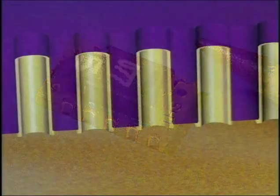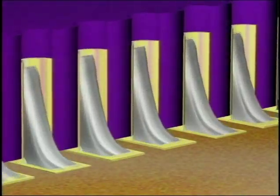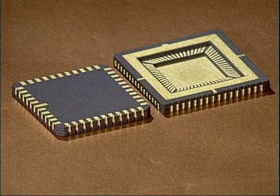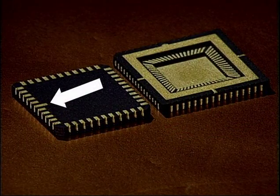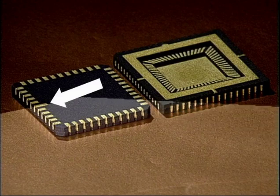As we mentioned earlier, LCCs utilize half-round metallized recesses in the side of the component called castellations. There can be up to 124 castellations on the larger LCCs. Like the leads on ICs, castellations are counted counterclockwise from the pin 1 orientation mark.